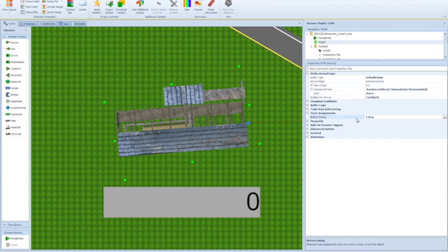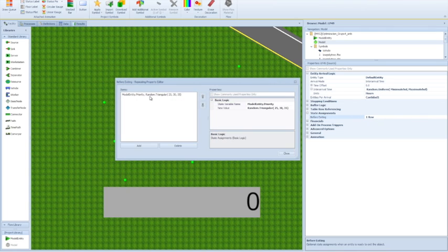First of all, we have the state assignments in Before Exiting of the source, where our model entity is changed to priority. This priority will save the weight of the lots of wood. In this case, we assign the weight with a random triangular distribution with a minimum of 25, a mode of 30, and a maximum of 35.